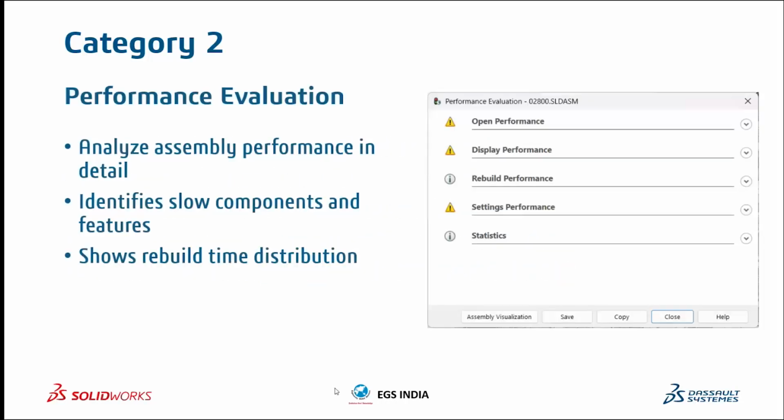And this is the most important topic, the performance evaluation. So with this set of features and with this set of suggestions that we've made, we can now check what other steps can be followed with this performance evaluation. So you can analyze the assembly performance in detail. It identifies which components take a lot of time to load, which takes a lot of time to open. It also shows which feature in particular takes a lot of time to rebuild, etc.